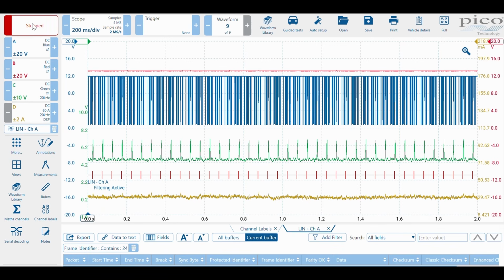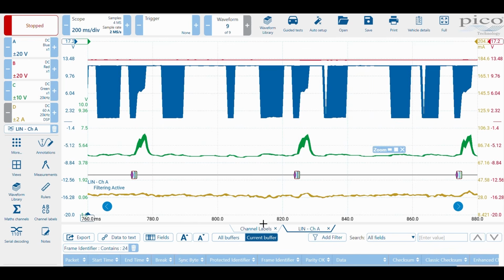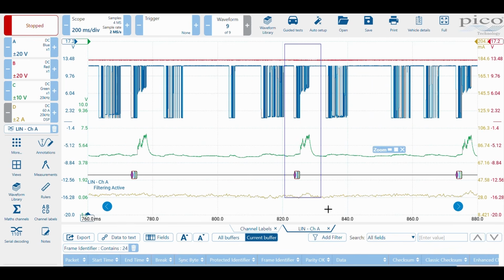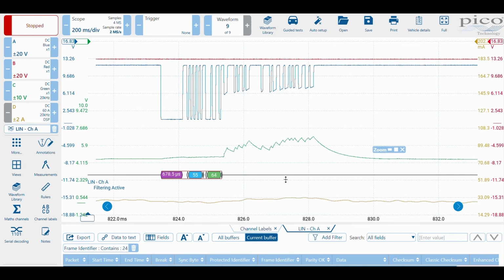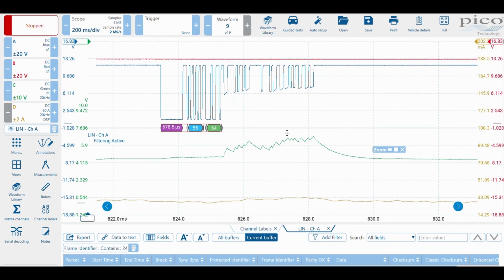So now where we had the spikes in the current when the resistance was good, now we've increased the resistance, we've got voltage drop present when the pressure switch tries to transmit. Let's have a look at what's happened to the voltage drop. Let's just zoom in on a couple of packets. Wow, I think that speaks volumes again, doesn't it? So there is the commander, there is the response, there now is voltage drop. So let's just scale up a little bit.